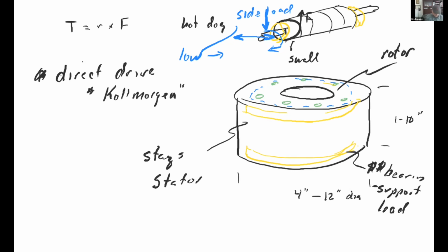You move up to a motor like this. This is a NEMA 34 motor. You guys have seen these before in 140. We use a lot of these. But all of a sudden, here is the bearing. You can see the big bearing in this. This actually, you can put a side load.